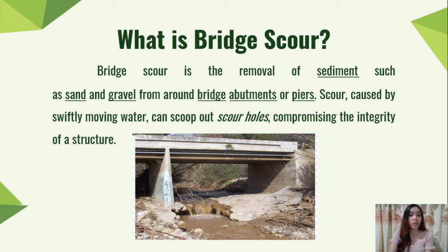In the United States, bridge scour is one of the three main causes of bridge failure, the others being collision and overloading. It has been estimated that 60% of all bridge failures result from scour and other hydraulic-related causes. It is the most common cause of highway bridge failure in the United States, where 46 of 86 major bridge failures resulted from scour near piers from 1961 to 1976. This is an example of bridge scour.